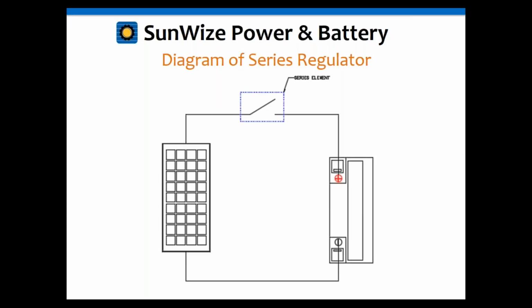So if you're checking voltages in a solar array and you're finding that they could be 0 or open circuit or something like that, you need to know what type of charge control you're working with and whether it's regulating or not, whether your battery's at a full state of charge, in order to understand whether it's working properly and whether there's really a problem with your system or it's functioning as it should be.